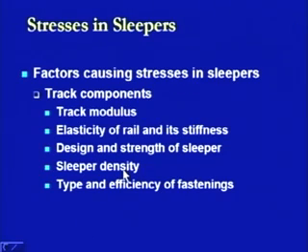Now, in the cases of the number of sleepers which have been provided, the sleeper density has its role. Though, as we have learned, the sleeper density has a smaller role in the case of the stresses being induced in rails. Here, if the sleeper density is more, it means the stress coming from the rail sections is going to be distributed to more of the sleepers, and therefore, the amount of stress induced in the sleepers will be lesser.